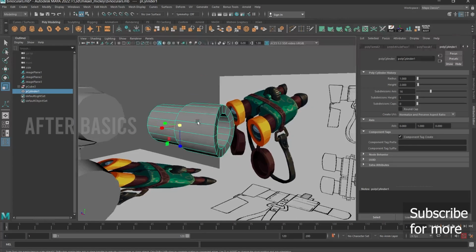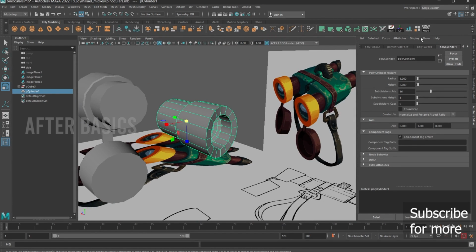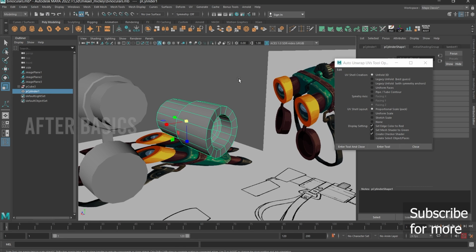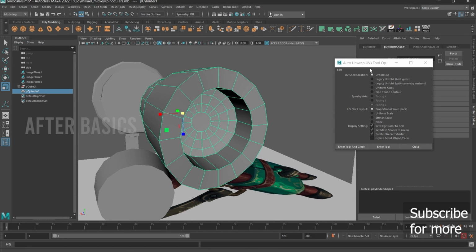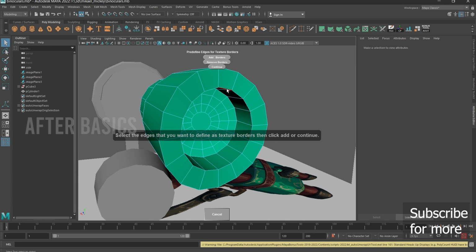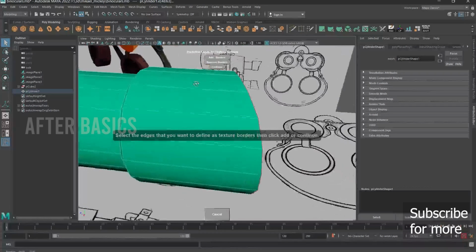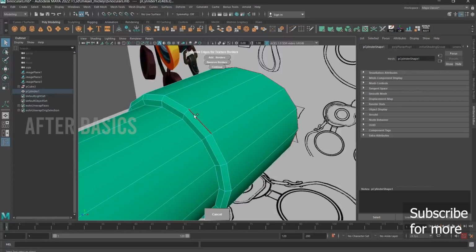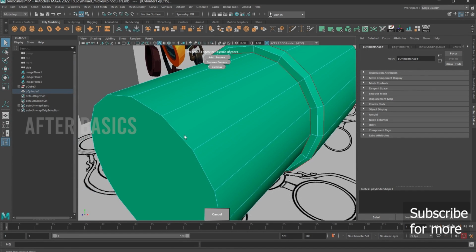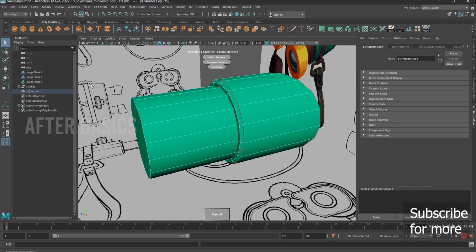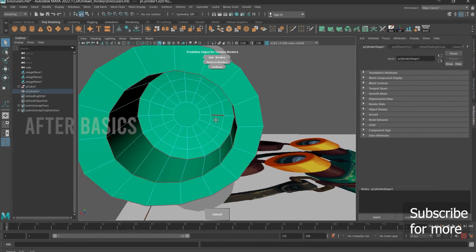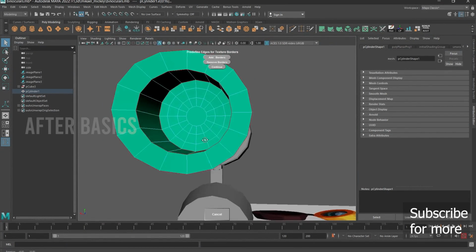Then the most interesting part, UV unwrapping. So I'm gonna delete all the history before I do that. Then entering it. So double click. Okay, and not on the top part, only on the bottom part. Okay, do like this. This is easy to do that. Okay, now let's go here, and we are done.